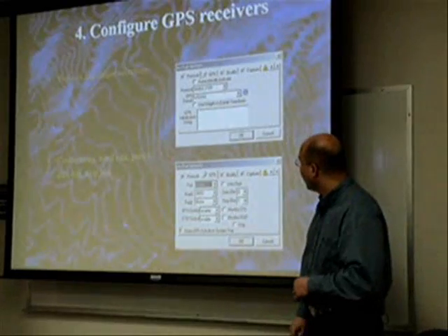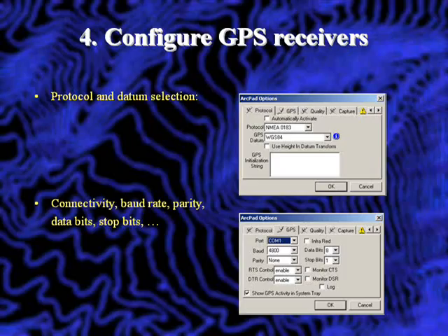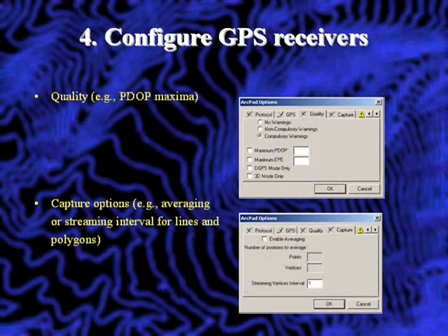That would be the baud rate. Data bits, how many stop bits do you have, parity, and so forth. You don't really have to become an expert in this. All you have to be able to do is read the help files and find in the program where to set it. The help files on the receiver, the manual on the receiver. Usually just open the manual and you'll find all these different settings that it requires.